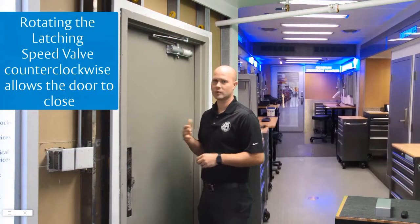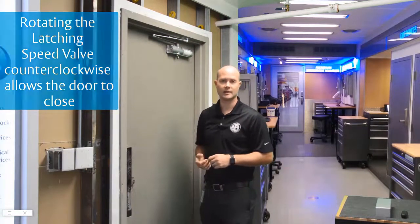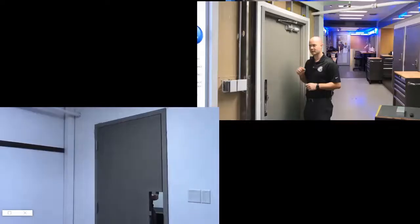Okay. So we're really close to having a perfectly adjusted door closer, but now we need to check it. So I'm going to forcefully push on the door to check my back check. Once we get our back check perfect, then I'll let the door close, and we'll actually use our watch to time the door closing from a 90-degree open position.